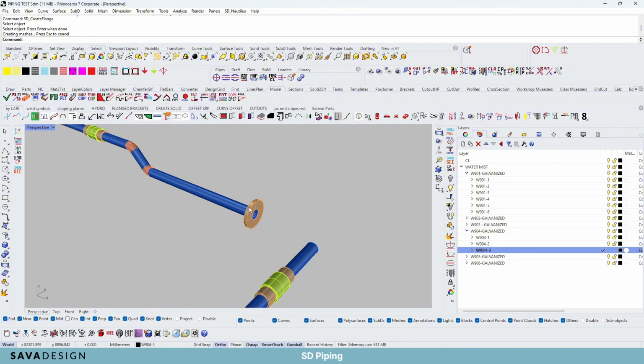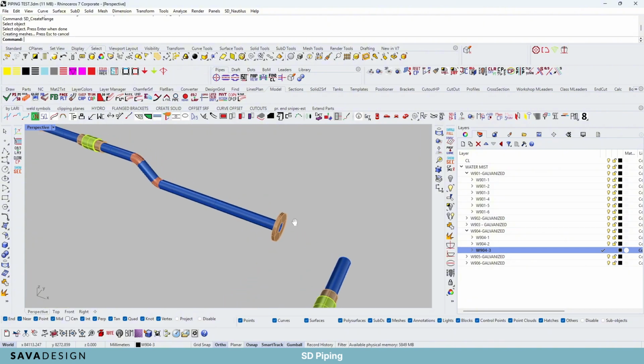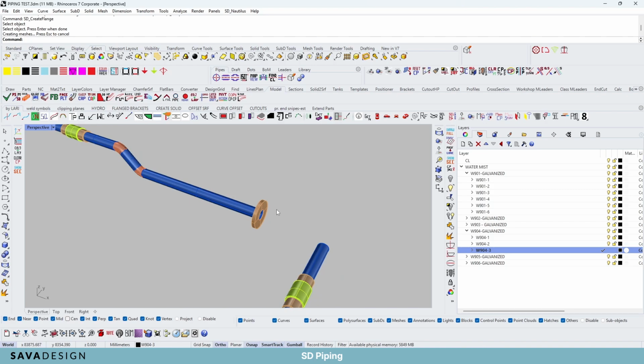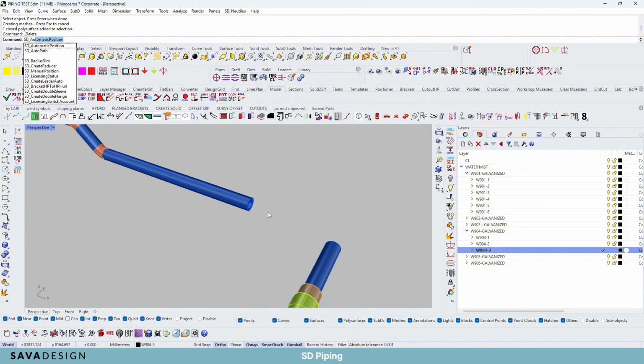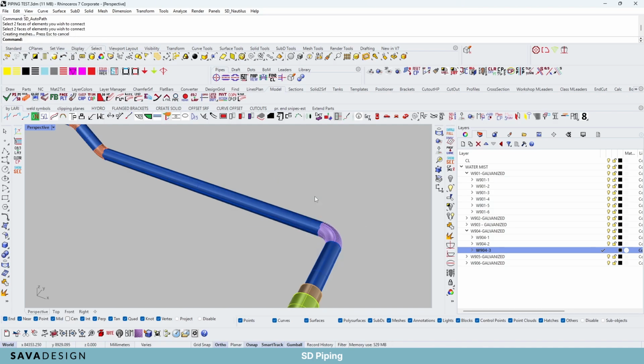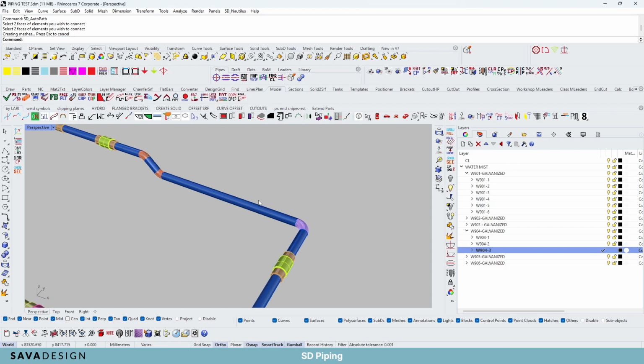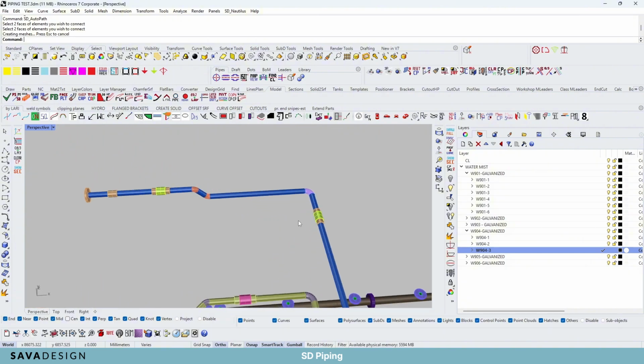Or we also have options to automatically merge lines. If you delete the flange wire, run auto path. It will attempt to find the shortest path. Of course, this is 3D space, so this one worked perfectly. Okay. So here you get the point, right? You can modify, you can play around with the line. You can cut it, add elements. You can automatically create paths between lines if you want to merge things. So it should give you enough freedom to basically model it exactly how you want.